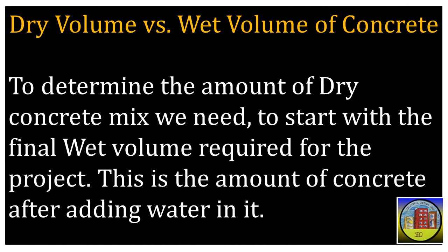Dry volume versus wet volume of concrete. In this slide we are going to know about dry volume and wet volume of concrete. To determine the amount of dry concrete mix we need, start with the final wet volume required for the project. Wet volume is the amount of concrete after adding water in it. Further,